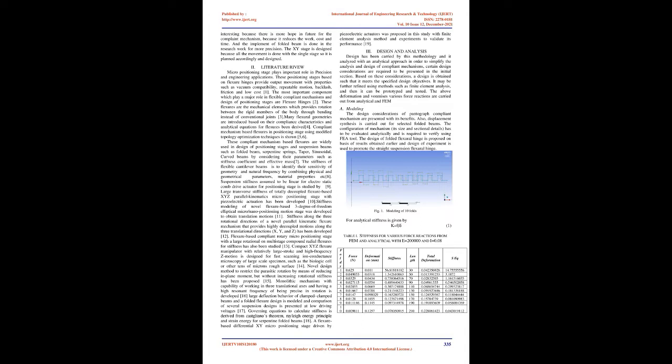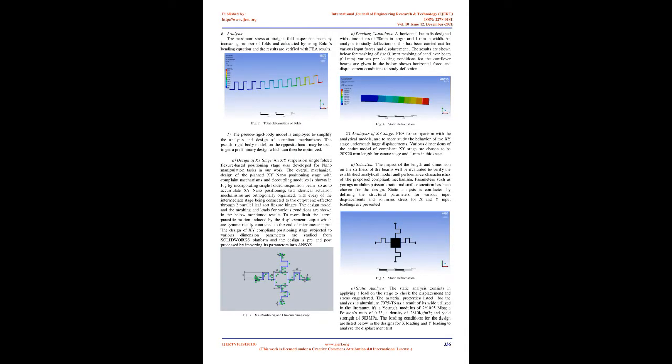studied. 13. A compact XYZ flexure manipulator with relatively large stroke and high-frequency Z motion is designed for fast scanning ion conductance microscopy of large-scale specimens, such as biological cells or other surfaces that are tens of microns rough. 14. A novel design method to restrict the parasitic rotation by means of reducing in-plane moment, but without increasing rotational stiffness, has been proposed. 15. A monolithic mechanism capable of working in 3 translational axes, having a high resonant frequency and being precise in rotation, is developed.